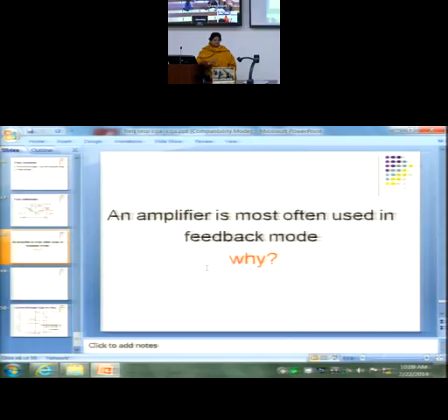Feedback mode, we can configure it for our own gain. Exactly. That I can do in common source also. Can't I configure the gain there? If I need higher gain, I can go for cascade. If I go for still higher gain, go for 2-3 stages together, maybe 3 common source amplifiers together. So what is it that benefits me when I configure an op-amp in a feedback mode?